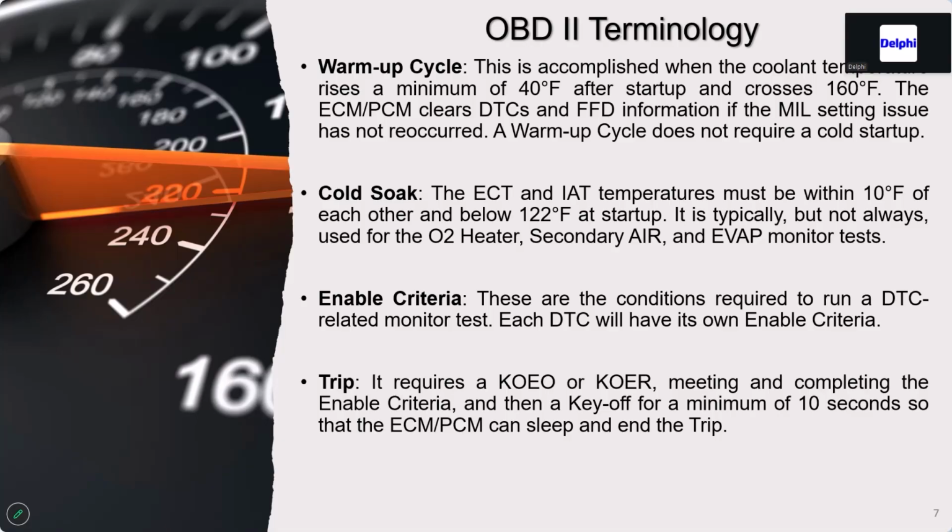Now, why do we use warm-up cycles? The PCM uses it to clear any existing DTCs that were left in memory if the issue has not reoccurred. The thing I want to emphasize is a warm-up cycle does not require a cold startup. So it's basically the computer's way of tracking how long any information has been in memory. It's also your way to know if somebody has been in the system before you got your hands on it. I'll show you a little sample later, but if you go in there and see 1, 2, 5, 7, somebody's been in there, or maybe they've had a dead battery, but somebody's been in that system. That's a clue that you're not getting this car firsthand.